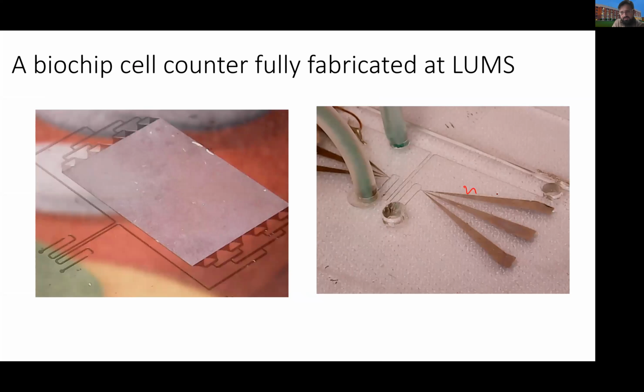These are the microelectrodes, and these are all microfluidic channels. So what you do is that you make the electrodes on a glass plate, and you make your microfluidic channels using a soft polymer, and then you bond these two things together, and that's how you make a contact between these microelectrodes and the microfluidic channel.